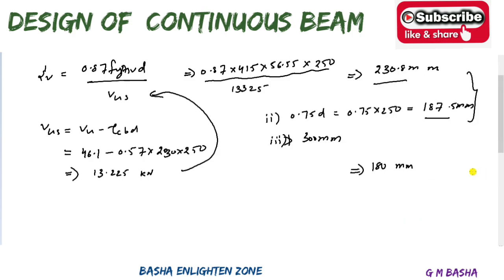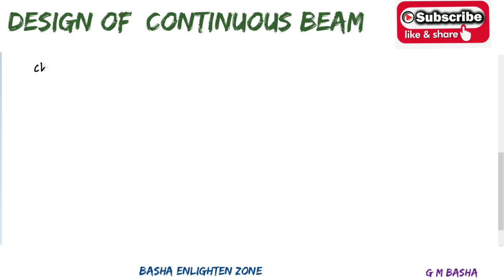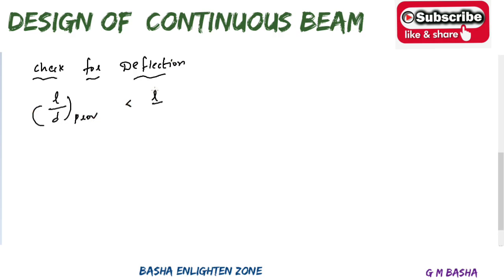Then go for the next step, deflection. Check for the deflection. How to check the deflection? Already I told you the formula: l by d provided should be less than l by d maximum. What is this l by d maximum? That is l by d basic into kt. I am not taking kc and kf because this is a singly reinforced section, where you only get tension reinforcement. There are no flanged beams, therefore we are omitting kf. There is no compression reinforcement, therefore we are omitting kc also.